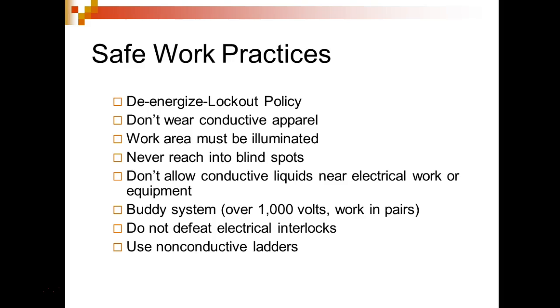U.S. Steel changed to say lockout only. They didn't require tags. One company I used to work for, you had to have a tag and a lock. At U.S. Steel, we didn't have a separate tag. You had to lock with a little brass tag. I think they put the information on it. So you did tag out, it's just that you didn't use a standard paper tag. They had a particular lock issued with lock cases.